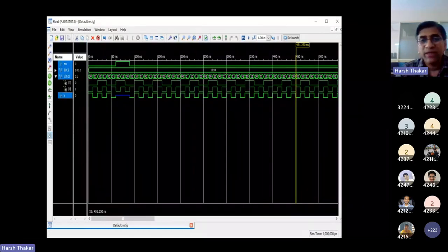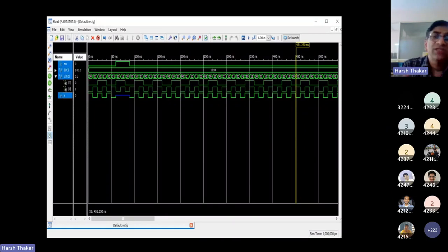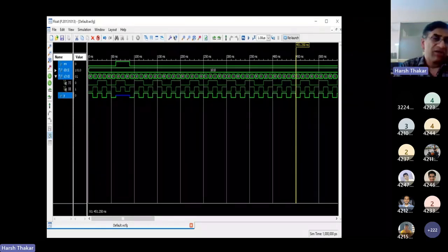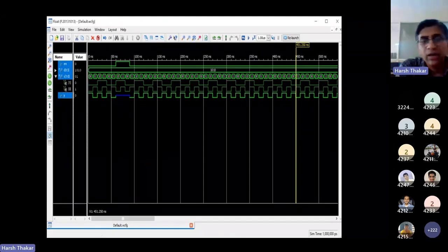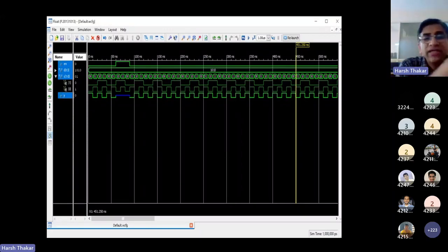So FPGA prototyping is nothing but we actually program the FPGA into what is called a PDS. PDS stands for proposed digital system, and that system can be as simple as a one input NOT gate to as complex as a fully functional microcontroller or a microprocessor. Okay, so for FPGA prototyping, just like you had used JTAG cables or download cables between your machine and the microcontroller kit, we also connect a JTAG cable or a download cable between our machine and the FPGA kit. And by following certain standard steps, we can actually program the FPGA.